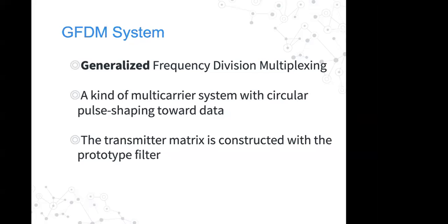And also we use a matrix notation. So the complexity of the system is also more compared to OFDM, because in OFDM, using FFT and IFFT, I can show my entire transmitter and receiver. Whereas in GFDM, I have to use certain mathematics to show what is my transmission and what is my reception, the data stream constructed with the prototype filter.